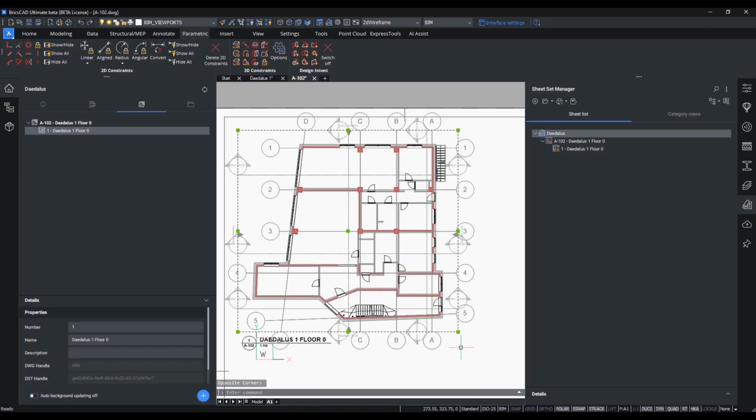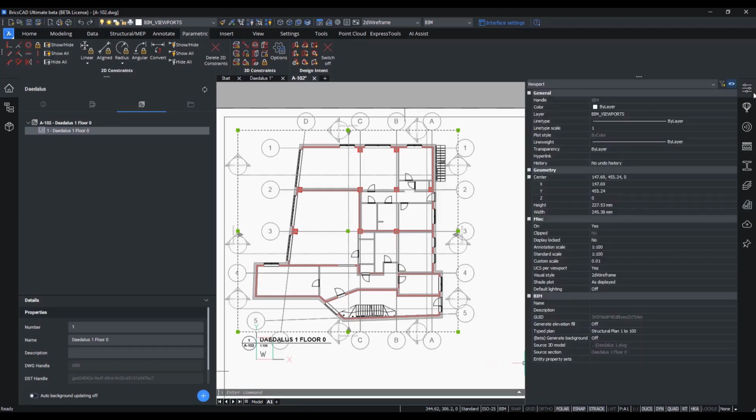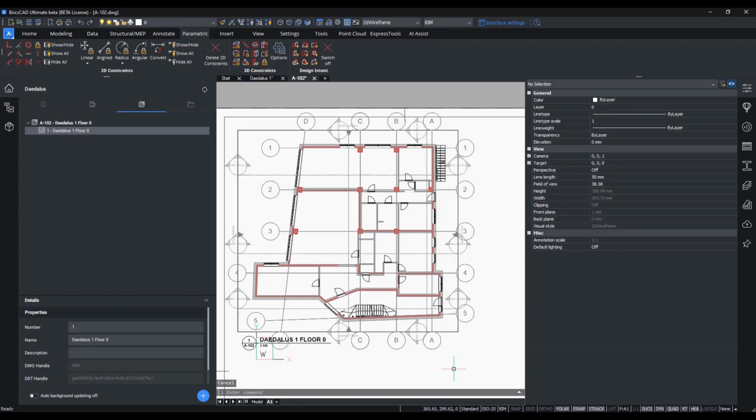The second method of creating a 2D drawing that follows a type plan is just that. Generate a 2D drawing, go to the viewport that looks onto it, and from the Type Plan drop-down in the Properties panel, choose a type plan present in your project. By the way, the list you see here will become longer as soon as we have imported a few other type plans. But first, let us inspect the generated drawing a bit deeper to see what changed.